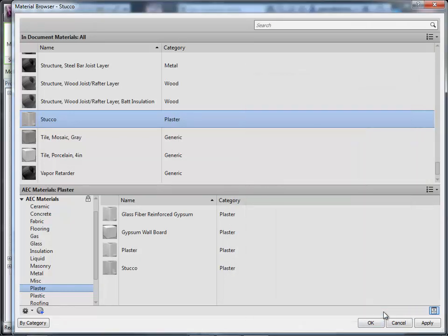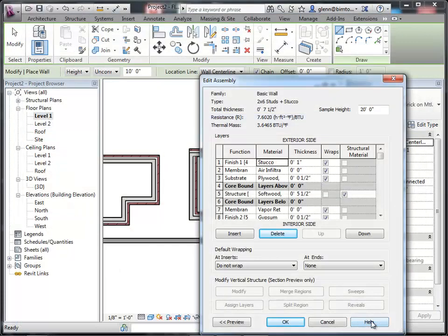But what I've been doing is really defining the appearance of something called the stucco pattern. So where are we now? We have been redefining a wall. We now have a 2x6 and stucco wall that has gypsum board, softwood, plywood, and stucco in there. And now if we use this, hopefully it's going to have the right thickness and also have the right appearance on the inside of that side.